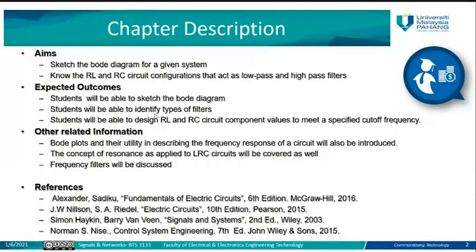For the filters, in this case, we are going to study the low pass and high pass filters, which consist of RL or RC circuits and so on. Also, we are going to learn how to design a filter based on specific cutoff frequencies. Previously, when we saw circuits like resistors, capacitors, and inductors, you just analyzed the circuit without any information about filters.